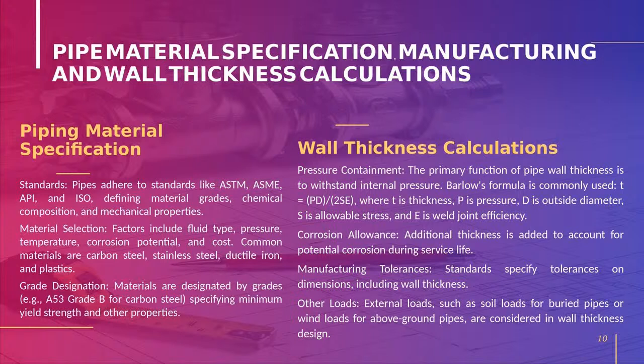So how much thickness is required for that instrument line? Based on the pressure, based on the temperature, based on the stress value. Stress values are given in the code book. So that we will explain to you in detail, and a sample calculation also we will show in upcoming sessions, how we are deriving a thickness. Okay, next slide, Soumya.